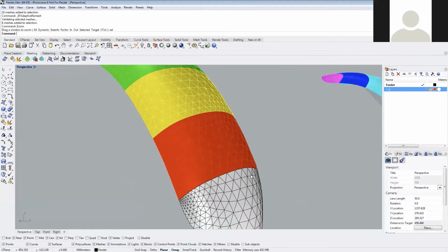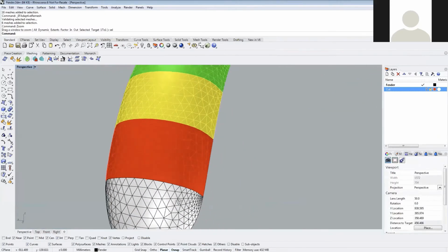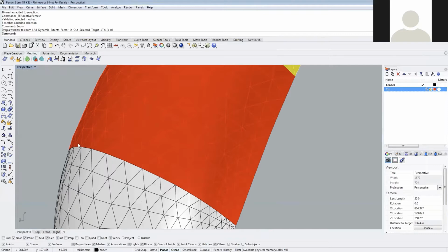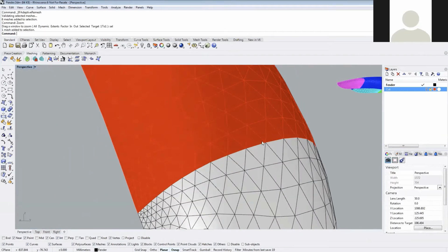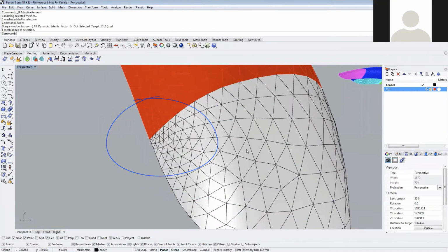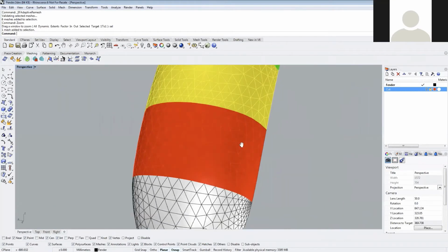When we look at these, the way the Adaptive Remesher has worked, it's ensured that we've got basically identical vertex topology between two pieces all the way along the cuts. So we've got very clean cuts here, and again we're seeing very nice equilateral triangles, and a very gradual change in triangle size. These are all characteristics that we want.